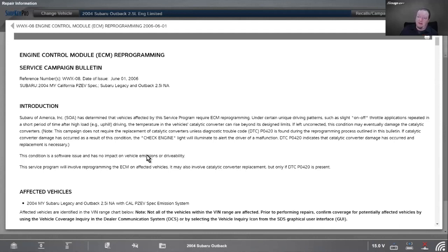Now, that's a really long way of saying we really leaned out the mixture a lot on the car in order to get our gas mileage. Whether they'll say that or not, that's what it was. So we're going to richen up the mixture a little bit, because I will tell you, we got a ton of people coming in after we did this and said, hey, my mileage just went through the toilet. And that's because they richened up the mixture. So it wasn't as lean and they weren't burning out as many cats.